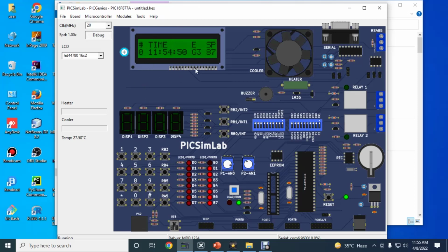So these are the log events which have been recorded: gear 3, C, GN, GR, G1. That's all. These are the events which have been recorded. So let's reset and again enter our password and clear our logs. For this, use this down key and select clear log. So the logs are successfully cleared. There are no more logs. To verify it, let's view the log again. So no logs have been found.